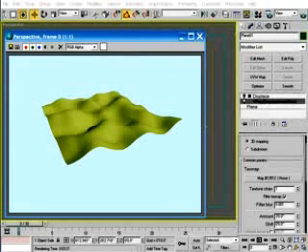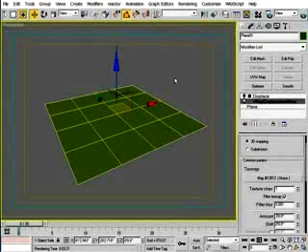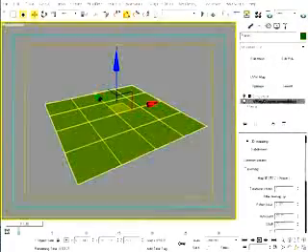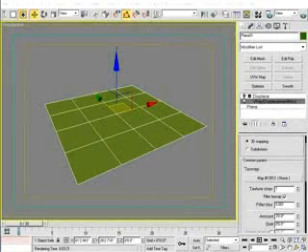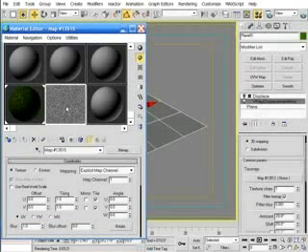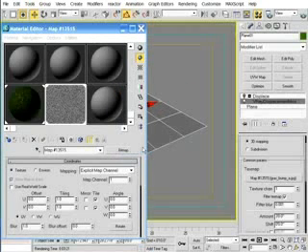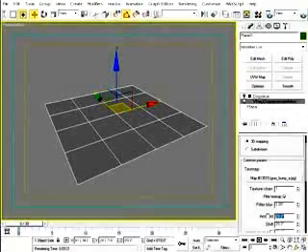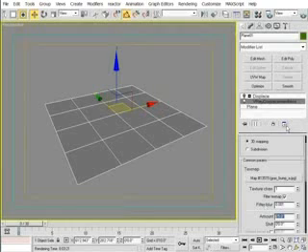Now let's look at an example where this feature really shines, which is in the simulation of 3D grass. I'm going to stay in the scene, which, if you want to follow along with, is entitled grass.max. In the material editor, I've preloaded some materials, one of which contains a really nice bitmap for the grass, and I want to simply add this material to the plane. Now, for the texture map slot in the VRay displacement modifier, I'm going to use this black and white bitmap which tells VRay the areas that need to be recessed and the areas that need to be raised. With grass, you want to stay with a displacement amount somewhere in the neighborhood of 4 to 6 inches. So I'll try 5 inches here, and when I render the scene,